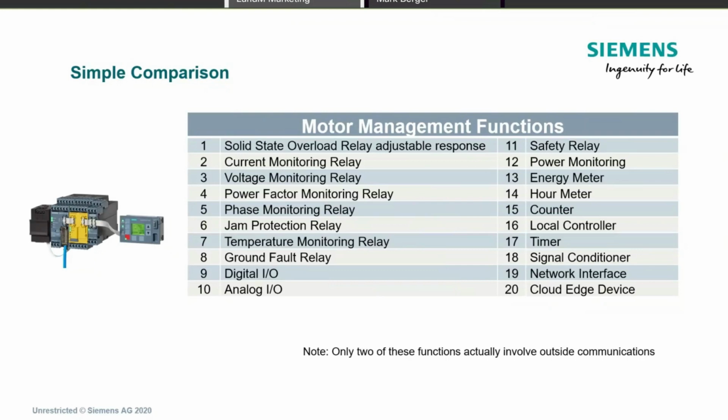Well, we could put an analog pressure transducer out on that pivot on the far point, set some process windows of the pressure in that system, and we could have the SIMOCODE trip if it sees that the pressure drops out of the nominal pressure of the process of the pivot, and trip so that nothing else happens, and then give a signal to let them know that maybe there's a problem with the pumping, but nothing wrong with the motor because it's not in an overload state. It's still pumping water, but we may have had a pressure drop or something had changed in the process of pumping water. Just an idea for that application of using an analog.